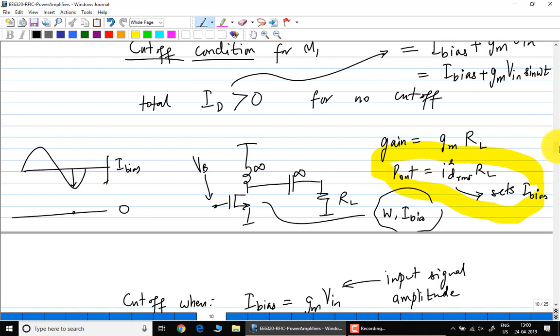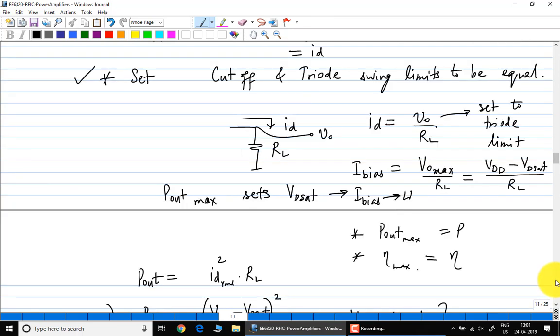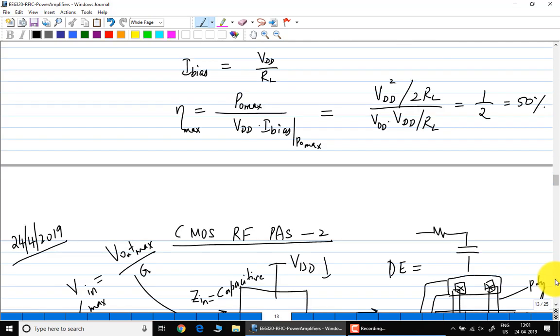So the MOSFET power dissipation, assume input is capacitive, is simply ID times VDS. I didn't explicitly mention that, but I think all of you know this, right? So the additional power goes into the MOSFET, where the power in M1 has average value of